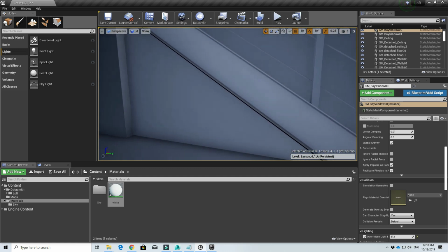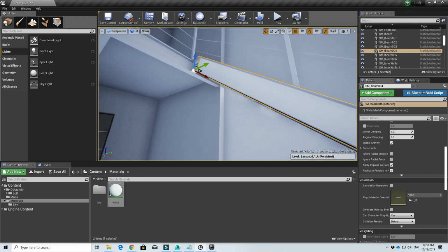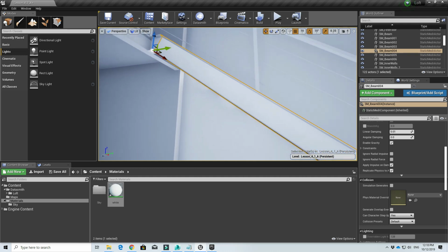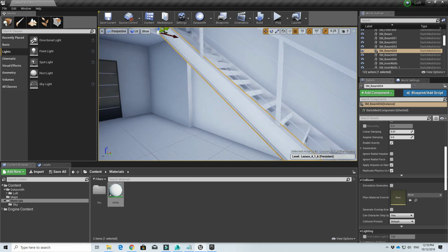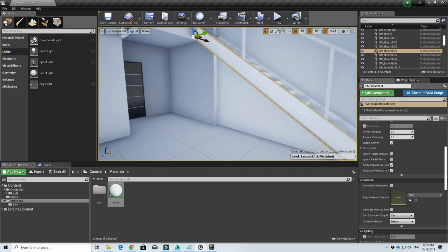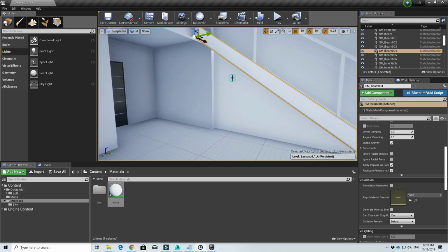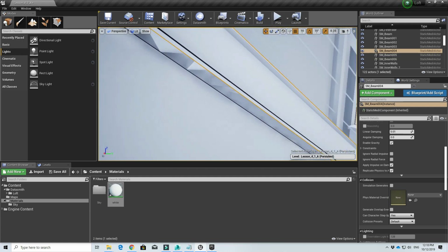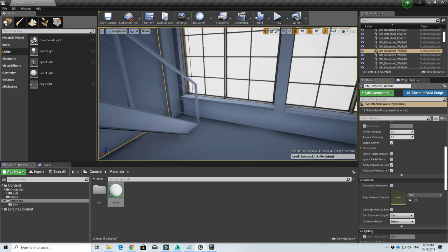So things like the I-beam, these are some light map issues, but because the I-beam is essentially black in color anyway, I will just leave it as it is and not do too much work. Another tip is that if you have a challenging mesh with some light map issues, then using a dark color to mask away some of these issues will help.